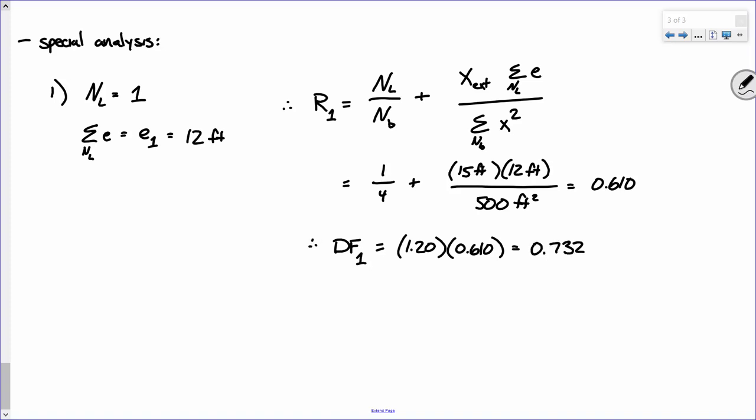...73, and we'll say what, 732? Yeah. Okay, all right. Let's clarify what this is for. This is for exterior girders. This is for moment and shear. And it's for how many lanes loaded? 1. It's just 1 lane loaded scenarios because it's a special analysis considering only 1 truck. So 1 lane loaded. Okay. So that's case 1. Any questions?